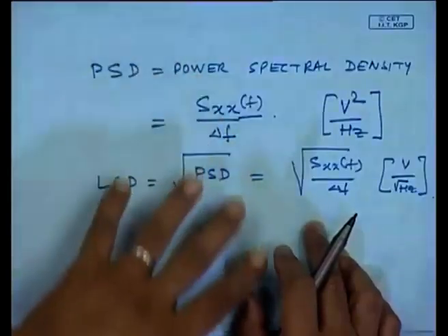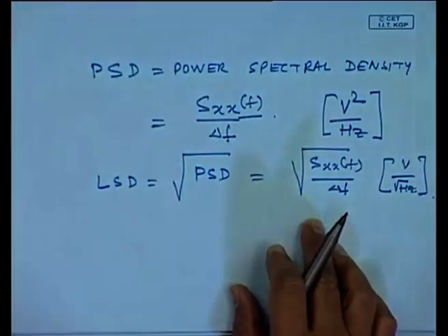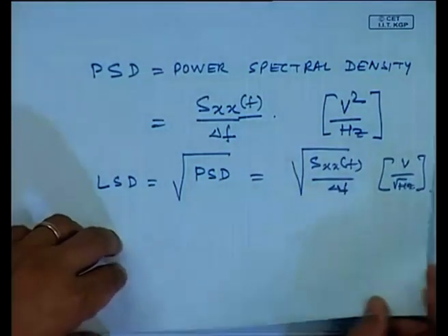Okay. And many of the FFT analyzers will have this availability at the push of a button, even in the software, but we should understand what physically they mean. So, we started with a signal x(t), we have seen how we have sampled it, got the blocks of data x(n), done FFT, got X(f), from X(f) we have got Sxx, and then we have got the auto power spectrum.